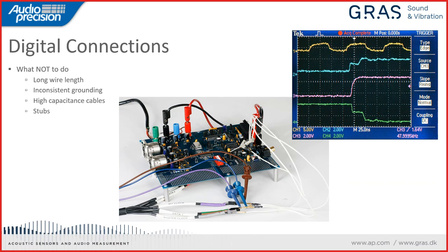So in general, keep your cable short as possible. Think about your grounding situation. In my particular case, I realize you can't see it physically, but I've carefully set up a star ground where the APX analyzer itself is the star, and I have ground straps for both the digital ground of the EVM and the analog ground of the EVM going back to it.